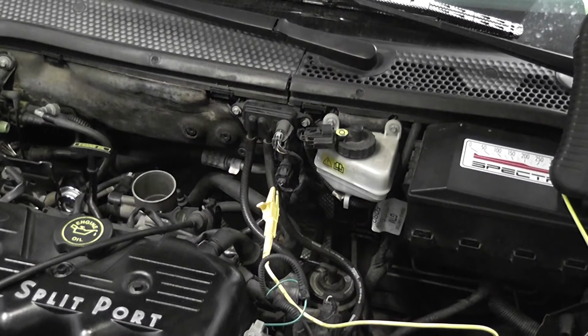If this circuit is being turned on by either a short to ground in the control wire or a shorted driver, that test light's going to light. You want to go ahead and do that for me? Test light's going to be to battery positive.